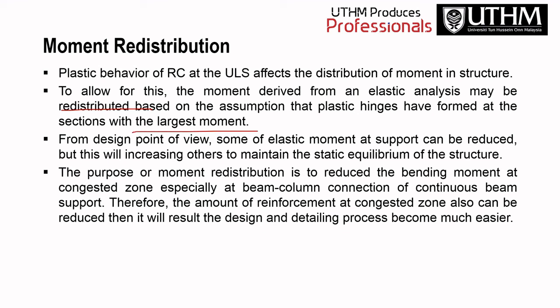From the design point of view, some elastic moment at the support can be reduced, but this will increase others to maintain the static equilibrium of the structure. The purpose of moment redistribution is to reduce the bending moments at congested zones, especially at the beam-column connections of the continuous beam support.